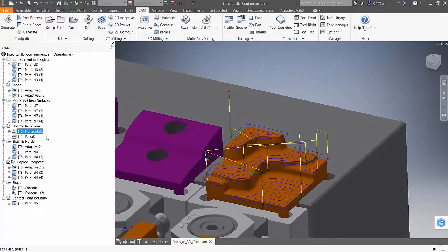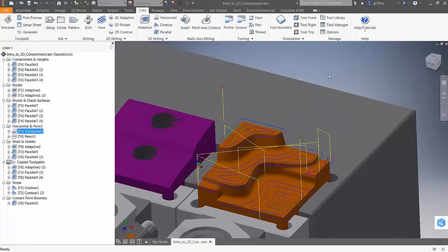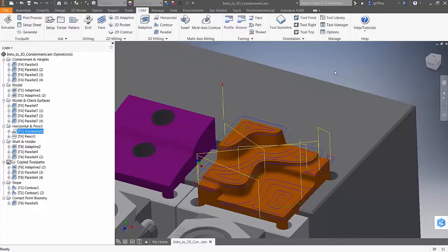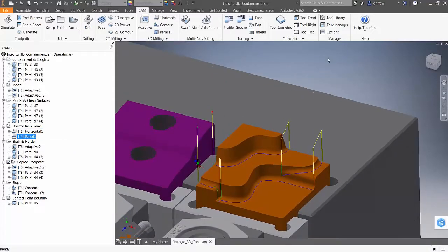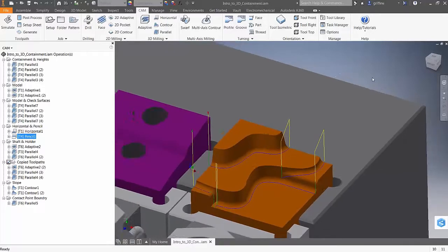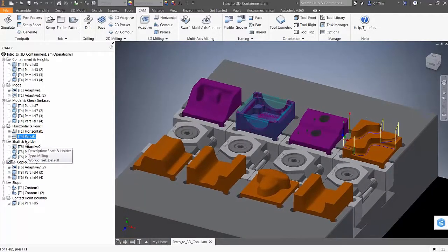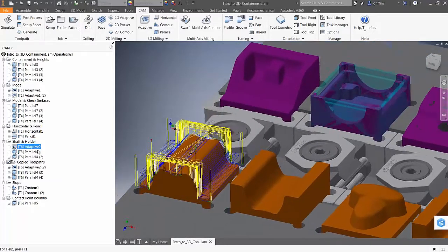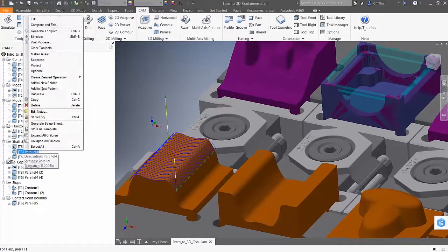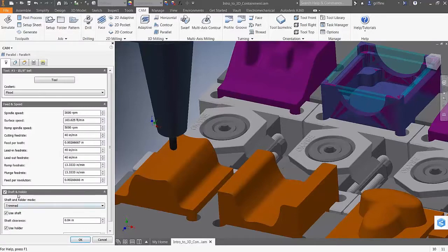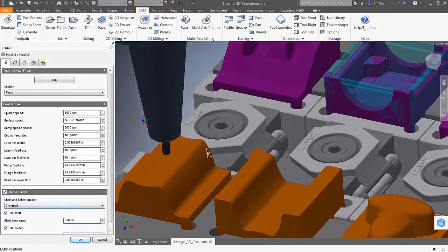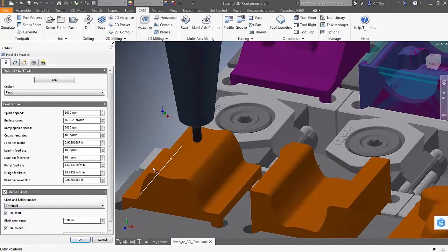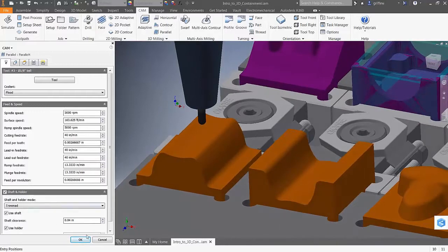So we have horizontal. These are toolpaths where they find their own containment, where it'll find all those flat areas where the tool can go most efficiently to remove that material. And pencil toolpath, again, finds its own containment area where it looks at those internal corners to apply. So in our shaft and holder, we're able to use tools like our model or our holder and shaft, where we can trim. We have other ways, pull away. We have other strategies where we can keep that tool or the tool holder from gouging our part. Another way to contain the toolpath.